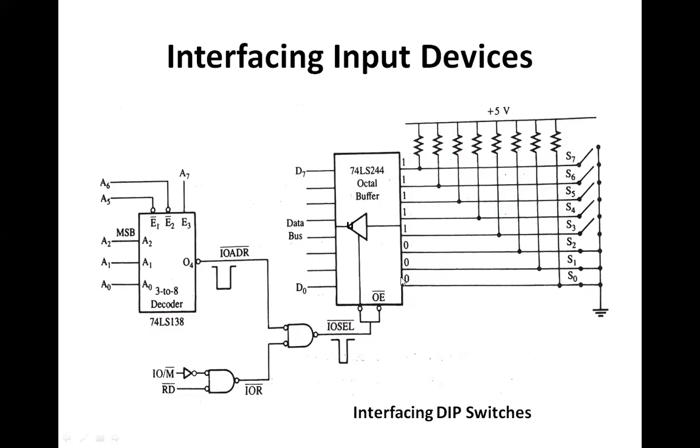So today we will be discussing the interfacing of the input devices. Of course, the instruction which will be used for getting the data or the information from the input device is the IN instruction. And this IN instruction is a 2-byte instruction, IN and the port address. So very much similar to the output devices, where whenever it is required, we used to use the OUT instruction.